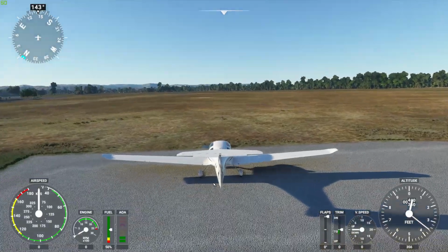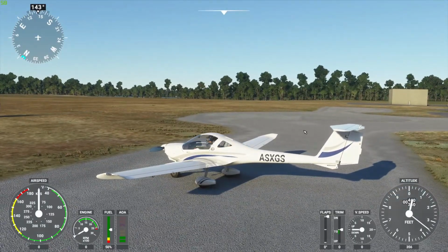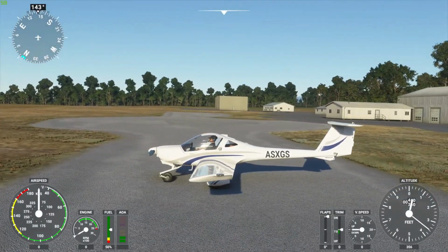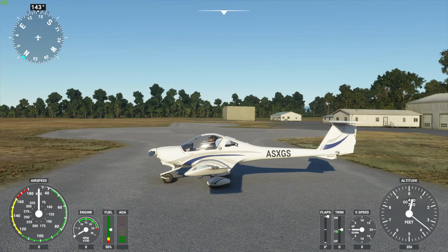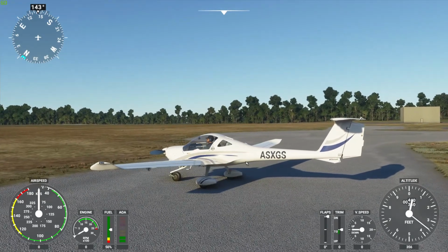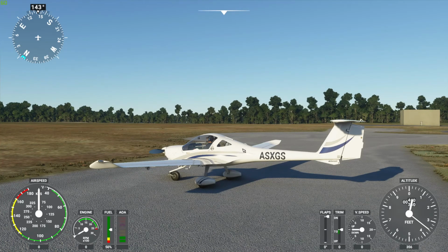So as I mentioned before, let's say we approach the aircraft for the first time on the outside, as of course we would, and immediately we have a bunch of information here. So I know it's built by Diamond, who've traditionally built gliders, so we can see this very long narrow tail means that it's kind of gliderish just in that look. So it's going to be quite a light airplane, mostly carbon fibre, and it is going to be potentially, because it's quite a skinny little tail there, we don't have a lot of surface area for gusty wind. So I'd imagine it could be quite laterally unstable in turbulence, but we'll see.